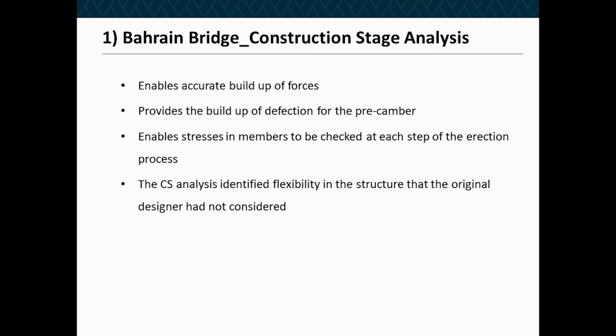Okay, so we used the construction stage analysis, and the following slide shows the build-up of this to calculate the pre-camber. Now, the importance of this construction stage analysis tool within MIDAS, as opposed to using other forms of software where you have to do it manually with different models, is that you actually get a true relationship and behavior of the structure as it evolves throughout the construction process, including the history and the build-up of all of the construction stage stresses.